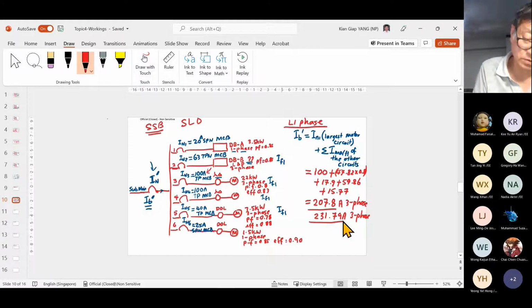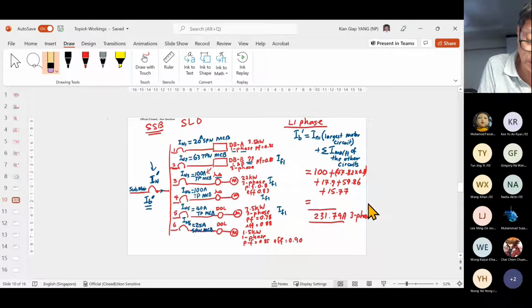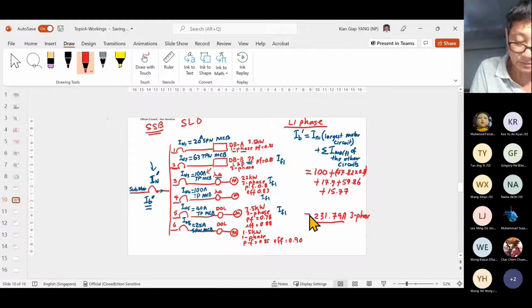231.786. Okay, so 231.79 is the correct answer. I'm wrong, huh? Kang, your calculator got a problem. You change your calculator. Oh no, I pressed wrongly. Okay, so what happened now is that my IB prime is 231.79. Then what should be my IN? IN must be greater than or equal to IB prime, right? So what is a suitable value for me to choose?